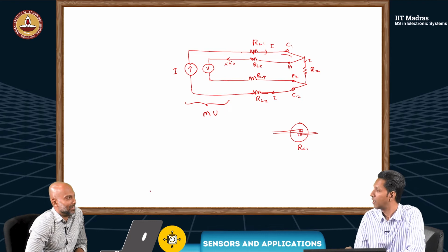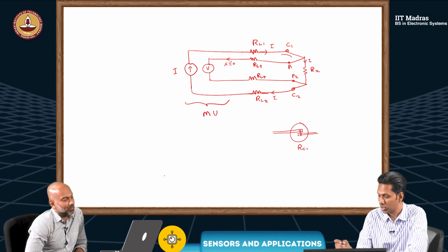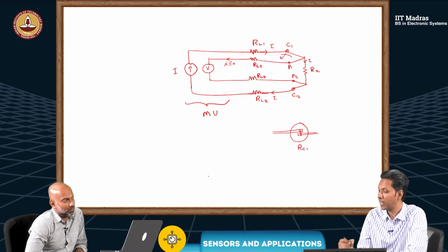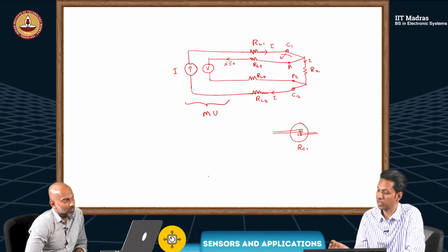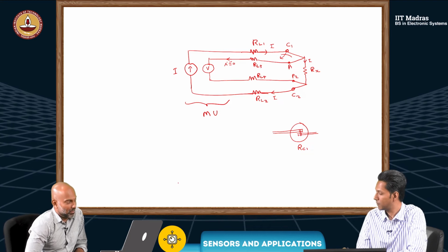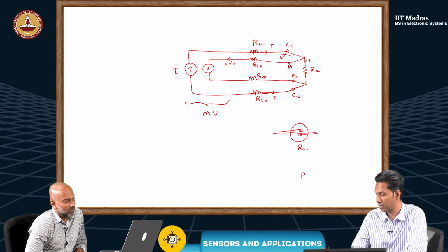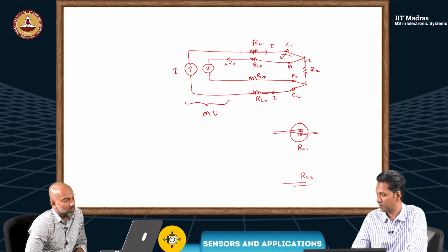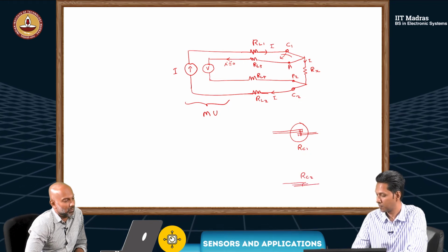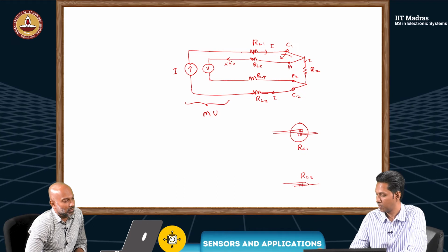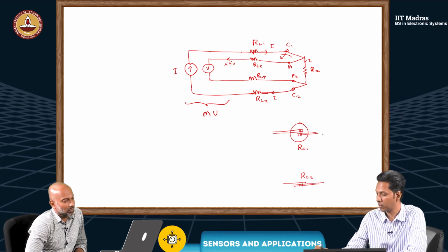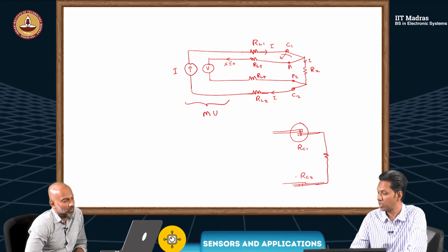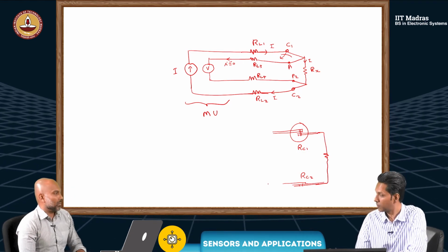So you're adding another resistance component. Suppose I am measuring the voltage from this terminal, then I will be measuring the voltage across Rx plus RC1. Similarly, at the bottom side, RC2. Not drawing properly, but I have this Rx here, and RC1 and RC2 come into the picture. You're introducing two more.